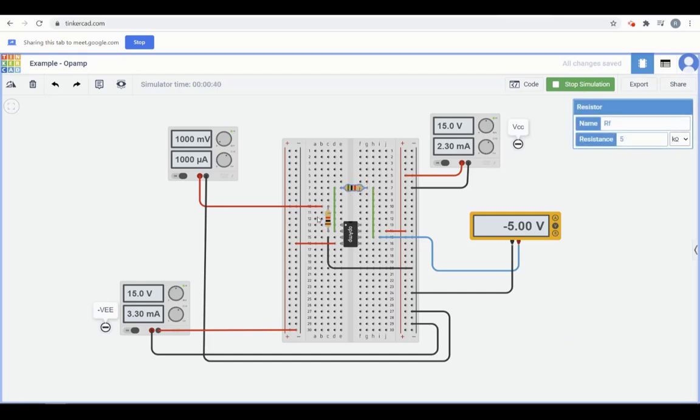The choice of these resistors was completely up to you. You could have chosen any standard values of such resistors. You just need to make sure that the ratio of their values results in a gain equal to -5. This is another very important advantage that op-amps offer to us: the entire gain now depends on the ratio of resistors and not on the value of the resistance as such. So all I need to do is maintain a particular ratio of resistance values. Doesn't matter what those values are.